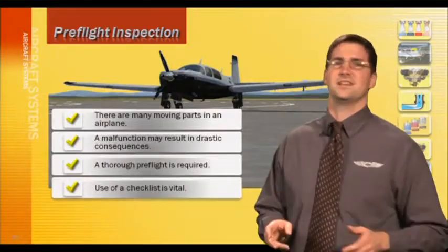elements, or even vandalism. Bob, we all know the importance of having a checklist, but can you give us some tips on a proper pre-flight inspection? I would recommend that people use their ears as well as their eyes as they move the ailerons and elevator during the pre-flight inspection. Listen. Anything that's operated by a cable or a push rod can develop little hitches. Listen for those things. Feel for those things.